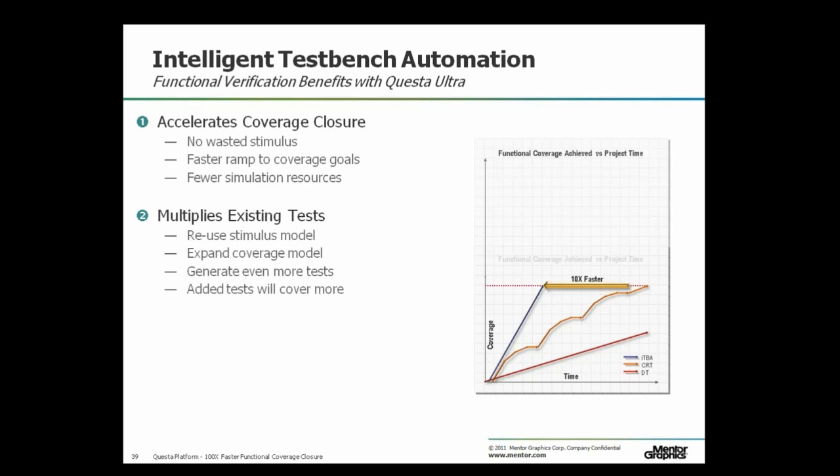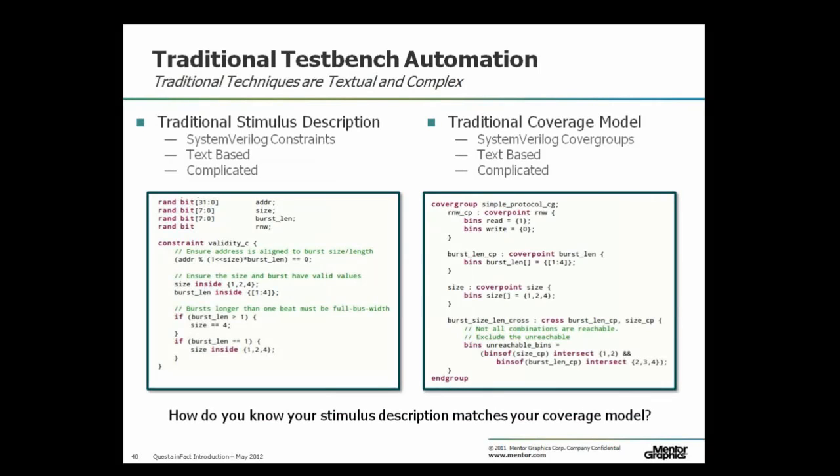You've probably seen slides similar to this that show directed testing, as we achieve coverage slowly in the red. Constrained random lets us start earlier, but then statistically starts to repeat and generate redundant stimulus. What the graph-based technology allows us to do is to start at the same ramp as constrained random, but to not slow down and to not repeat or produce redundant stimulus, unless you want redundant stimulus, because you can do both and combine them, and I'll show you how right here.